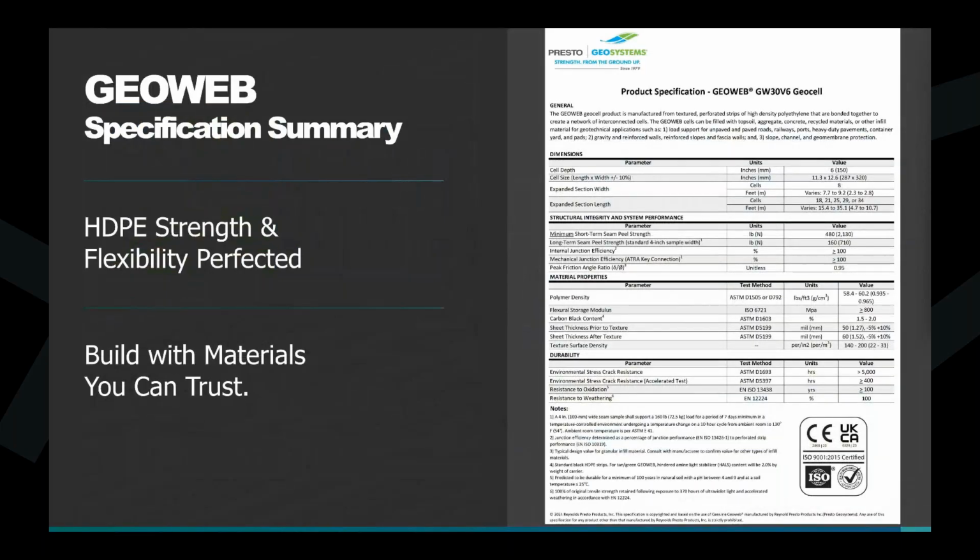And like I said, the GEOWEB system is manufactured from that high quality virgin HDPE resin, and it has proven its durability over the past 40 plus years. So the GEOWEB panels do not contain any fillers. So there's no calcium carbonates, recycled materials, polymer alloys, things like that. So the GEOWEB system has been designed to last over 100 years, and we've done lab testing showing it can withstand up to 149 years before there's any carbon black degradation, and that's even with continuous 24-hour sun exposure, which is obviously not how the real world works, but let's make those tests as extreme as possible.